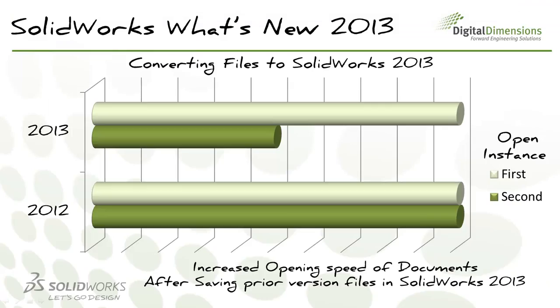So as we're talking about converting files to the latest version of SOLIDWORKS, I just want to remind you all that after you convert files to the latest version, you cannot open them in any older SOLIDWORKS versions. The exception to that is going to be our next topic.